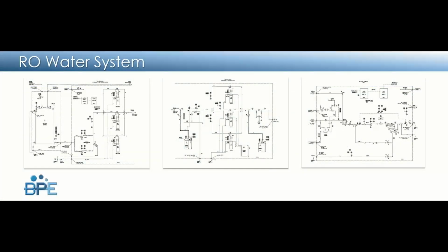And from a P&ID standpoint, this is really the pretreatment in this case. They're coming off the city water booster because of pressure. You have your multimedia beds for particulate removal. You have your chlorine removal here. There's actually a metabisulfite injection in this case. You have your water softening to soften your water, which we discussed in great detail. And then your brine tank is located down here.